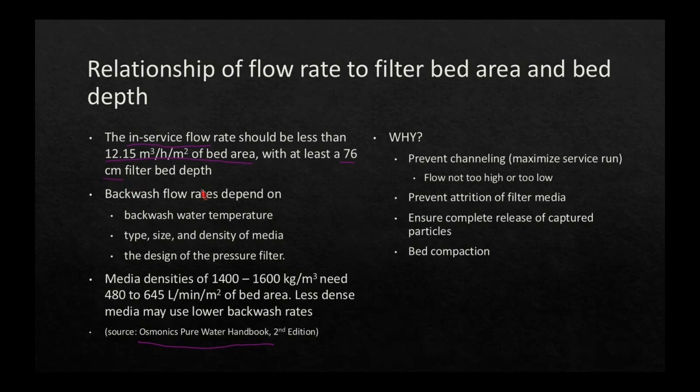So you're saying typically a 76 centimeter deep bed that has 1 square meter of surface area would be 12 cubic meters per hour.